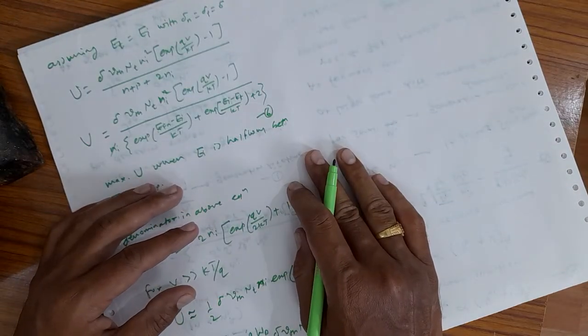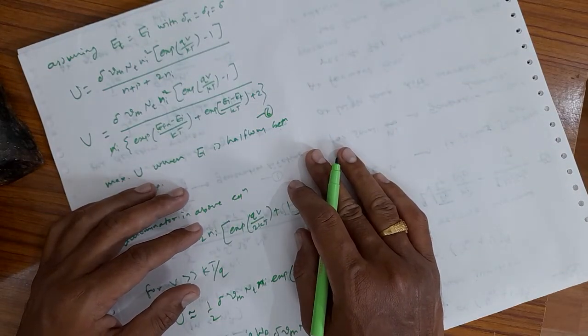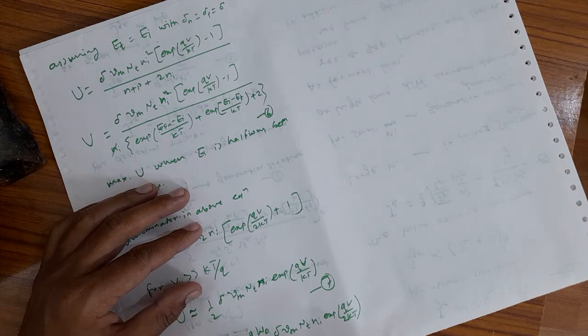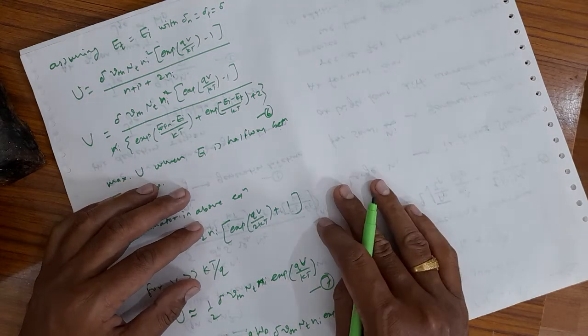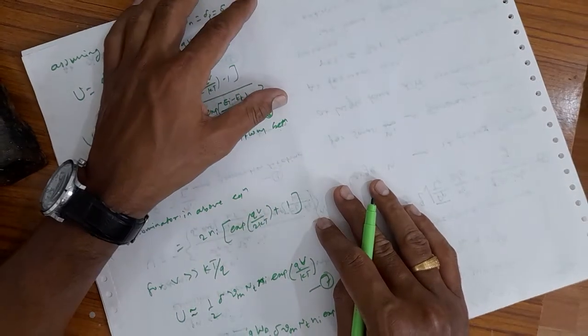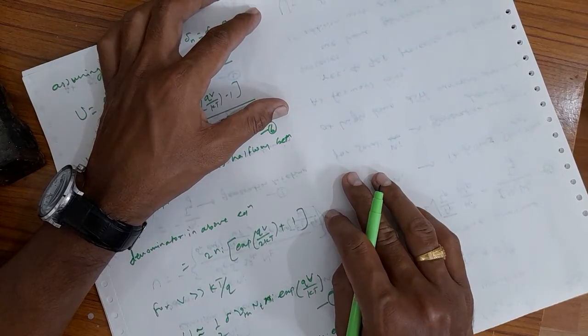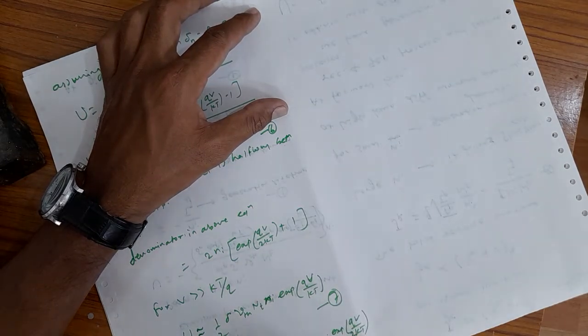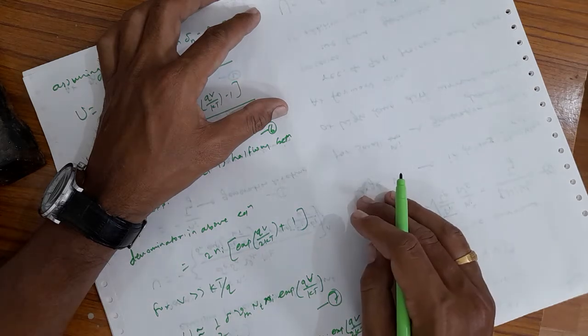Here we have assumed that most of the depletion layer has the maximum recombination rate, and this JRE, the recombination current, is somewhat an overestimate.